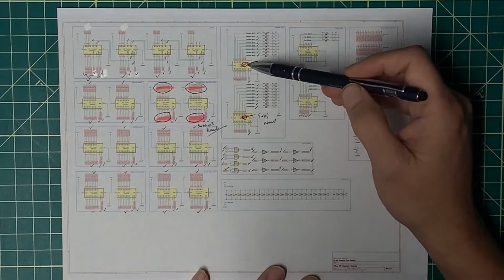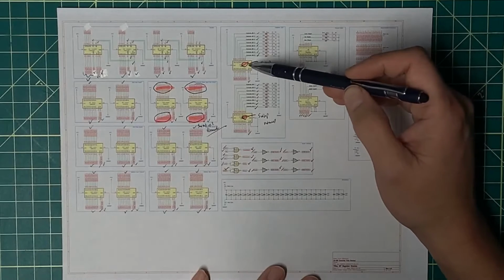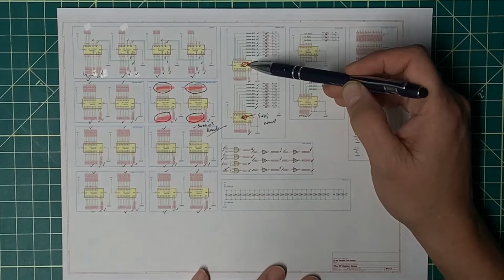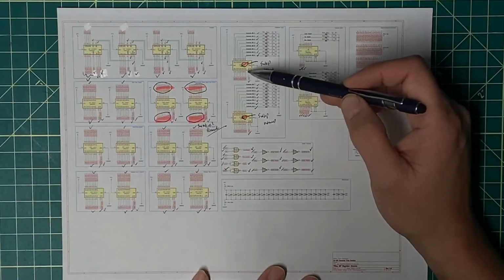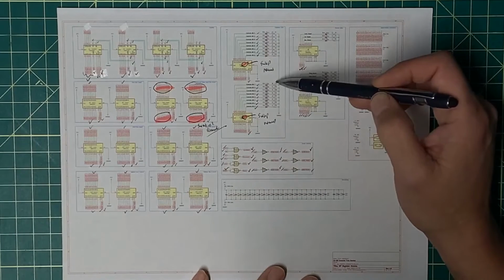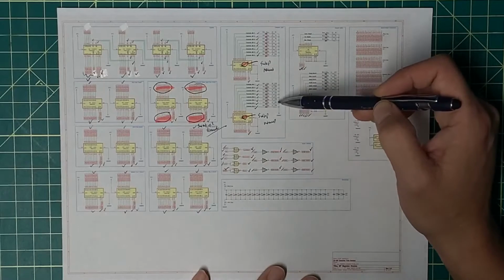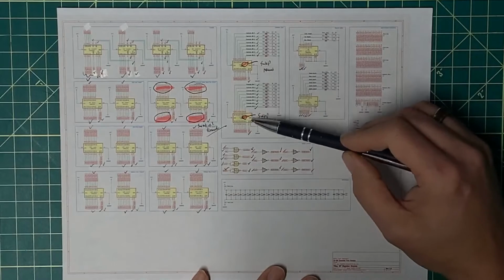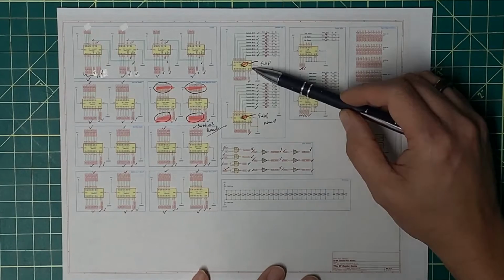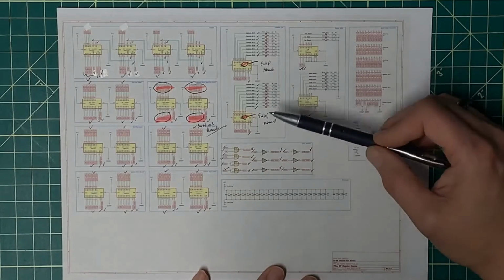The second is in the naming, and this is going to also impact the code. I've got LED 0 named associated with the most significant bits on the contents, and LED 1 named for the least significant bits. And that naming convention should be swapped as well. So I need to swap that both in the schematic, and I also need to swap that in the code.